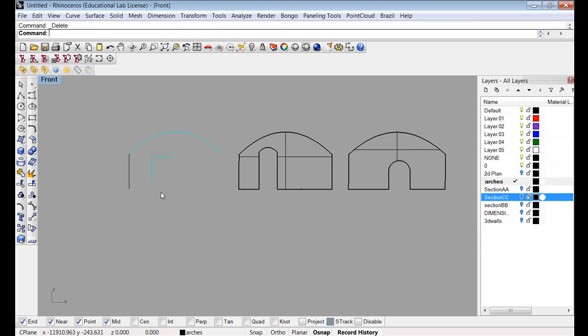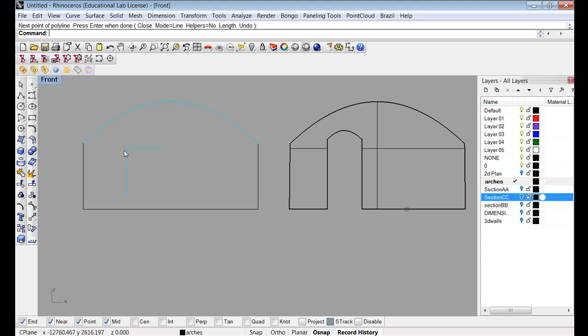So I can get rid of that line, and I can use this tool up here, my polyline, to click, and then if I go up there, that will reference down. Click there, press return to complete, and again, if we go across there, I go up to there to get reference.